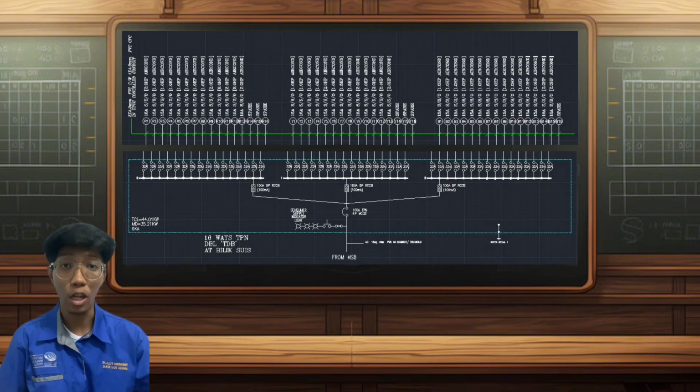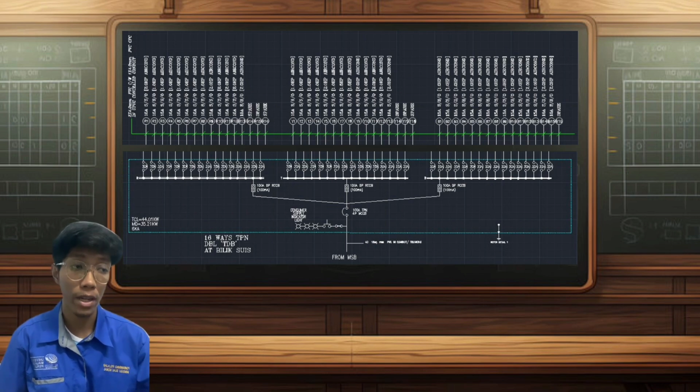For the MCB selection, we just follow the JKR specification that's suitable with aircon part, which is 32 ampere. Besides, we use 15 ampere socket to supply the load to the aircon with its type that we already chose, such as 1 HP, 1.5 HP and 2 HP aircon.